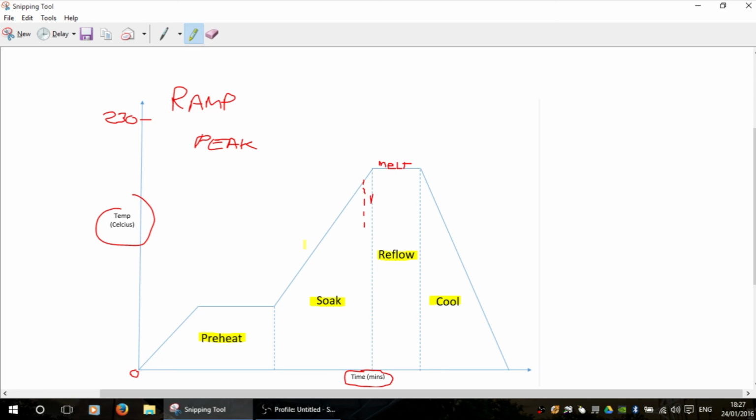So a good rule of thumb is to cool the board down, the BGA down by roughly 1 or 2 degrees a second till it gets down to around 100 Celsius. By that point the solder is well out of the way of its actual reflow point, and it's just then residual heat in the board, so that's when I actually like to add some induced cooling. So we'll add the cooling fan from the BGA Rework machine to actually get the temperatures down as quickly as possible back to room temperature. That's purely a time-saving sort of thing.